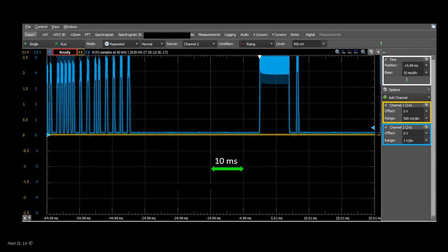Two most common data coding formats for remotes are non-return to zero and return to zero. More interesting is to look for the initial block known as preamble. It is a signal like a whistle to call for attention. The appliance demodulation and decoding to get the message is based on this preamble. This example shows a 10 millisecond preamble. Another standard may be different.